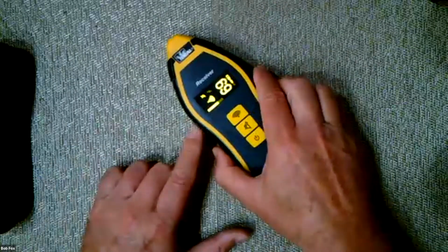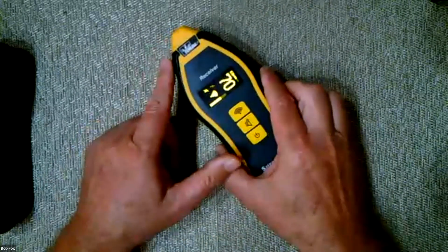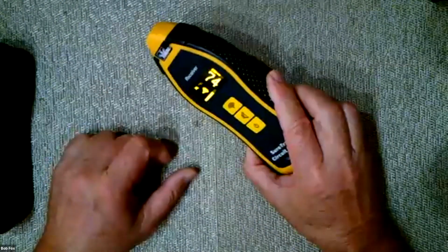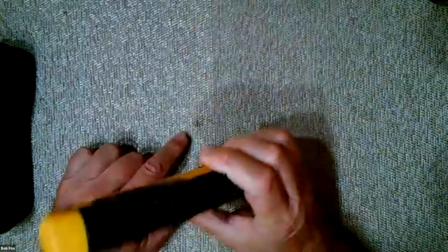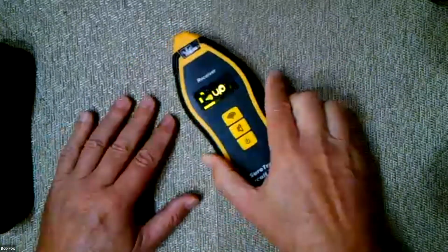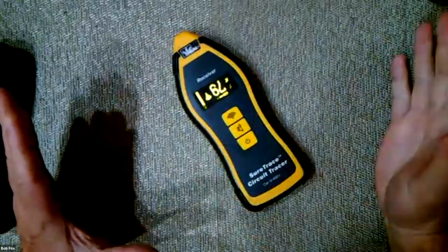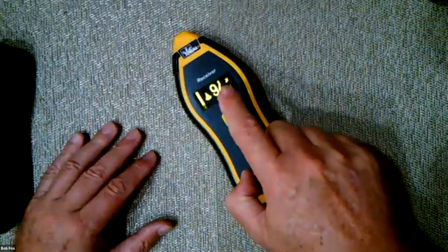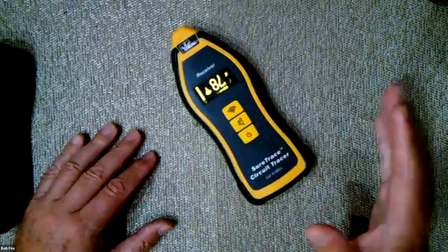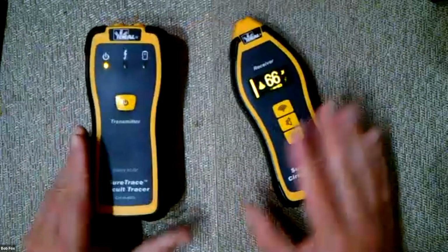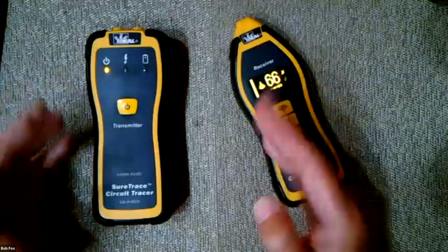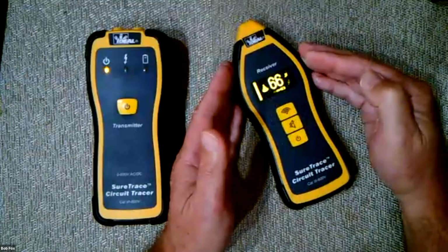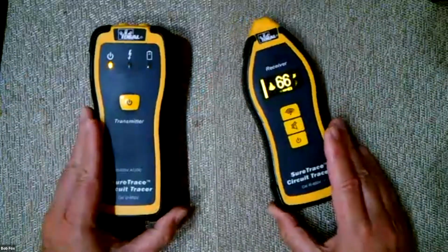And now you've confirmed, people say it makes no sense that it's pointing this way. And unfortunately, it looks like an arrow. So people say, oh, it must be over there. Oh, it must be over there. Oh, it's back over this way or up there or up here. Don't do that. Keep it flat against the surface when that's appropriate, or over the ground, for instance, and then find the orientation that gives you the strongest signal. Tracing is all about broadcasting a very strong signal and then receiving that signal. And that's really the trick to keep in the back of your mind.